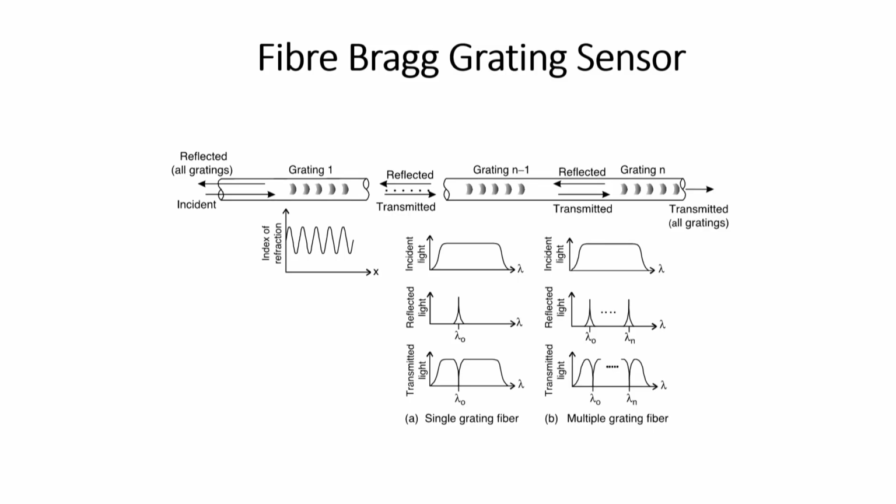Now, in the optical fibers, there is one interesting application that I will first start, and that is called fiber Bragg grating sensors. You know about the Bragg grating. The grating is something that you can do on the optical fiber. You can create some kind of etching in it, so that this etching can actually create a diffraction. Now, the etching, the distance between these gratings is directly related to the diffraction it is going to generate.